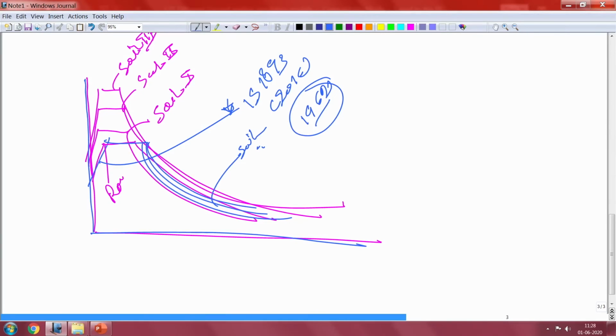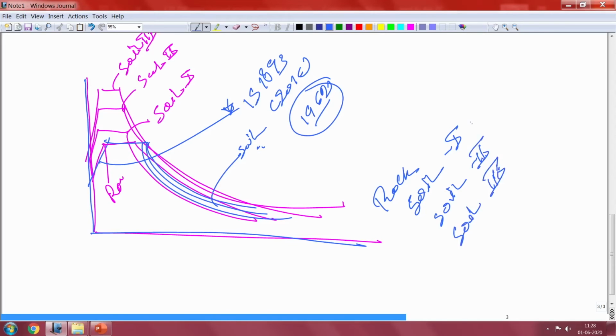So, what we are doing is collecting acceleration time histories of the different available earthquakes in India, and then trying to characterize that earthquake data as rock and different soil classes. Right now, since you have not studied soil classification as part of your course, I just give you a glimpse of soil 1, soil 2. These are basically different in the height or thickness of the soil, and then the stiffness. This will make these classes. Similarly, rock is different from this. So, we characterize the data we collected and group it according to which category it falls in. So, there is a systematic analysis and process.